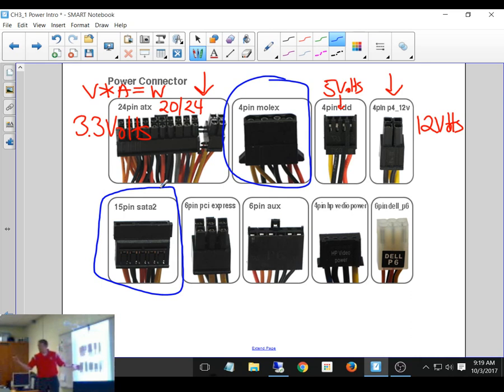So if my power supply is short of a connector, I can buy one of these on eBay for 99 cents. If I'm short the other way, this one turns this one into that one. Okay? So all I need is a little tiny adapter, and if I'm putting in a new motherboard and I've got a power supply that still seems to be working fine, but I don't have the right plugs on here, because if I look at this one, I've got 2 of these SATA plugs, but everything else on here is a Molex. I don't need Molexes. That's okay. All I have to do is buy some of these, and it just plugs into the end. If I put it on the right way, plugs into the end, and now I got another SATA connector.